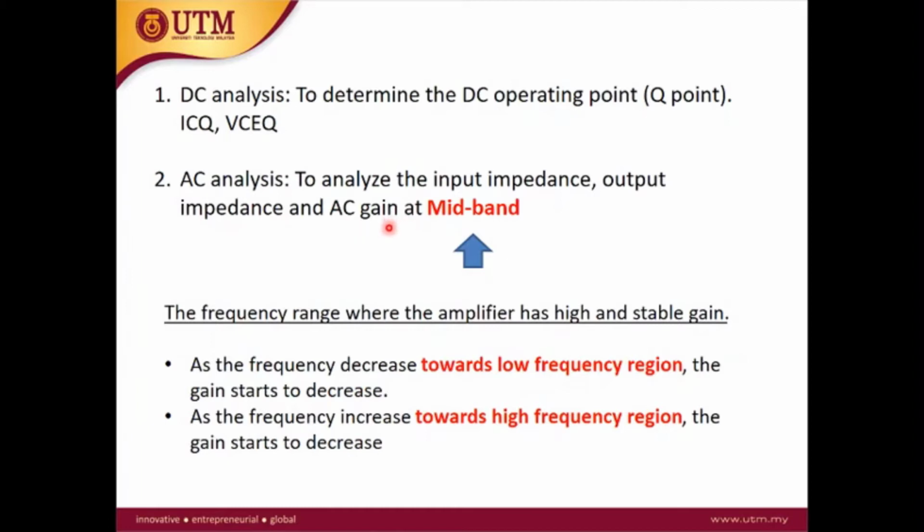For this AC analysis, we make several considerations when drawing the equivalent circuit. For example, we replace the capacitor with a short circuit. This consideration is for the BJT amplifier operating at the mid-band region.